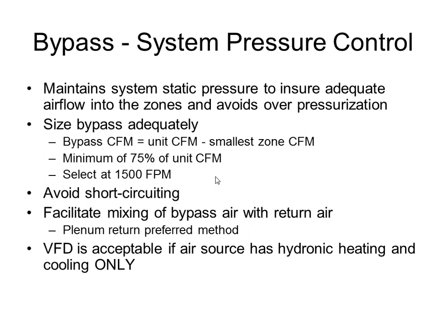And because of the size and the tonnages that are available, that we generally recommend for VVT, most air sources don't come standard with hydronic heat or cooling, or digital scroll compressors for modulating cooling or modulating gas. That's why it generally doesn't come up using a VFD, but it is possible. We say you can only do it with hydronic heating or cooling, but you can also do it with a digital scroll or any type of modulating cooling or heating. So it is possible.